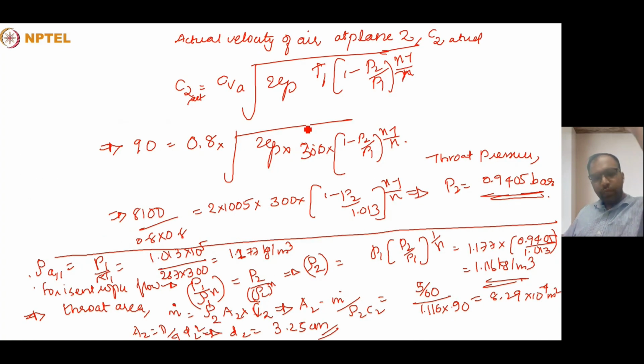The pressure at the venturi we calculated based on the isentropic flow. The density and the pressure are related by the isentropic flow equations.